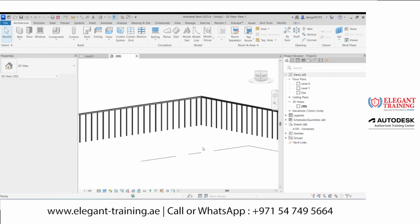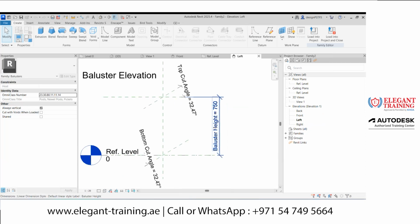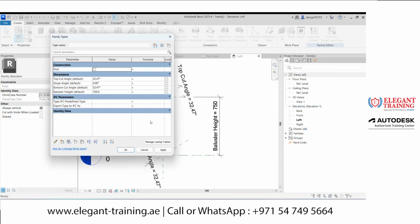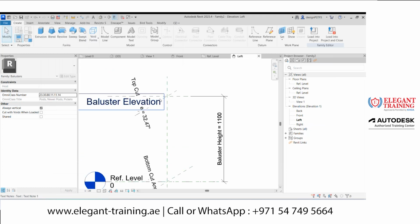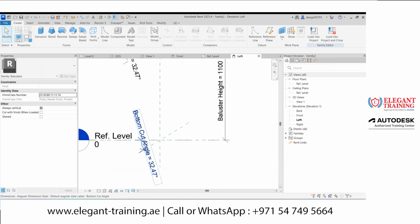I open. According to this template, here I can give the total height. The baluster height at present is 750, so I'm going to change this to 1100. You can go to Create and click this button, Family Types, and from here they already have the parameters. So let me change this to 1100, so that this is the height. Your top rail will come in this part and your bottom rail will come under this part.